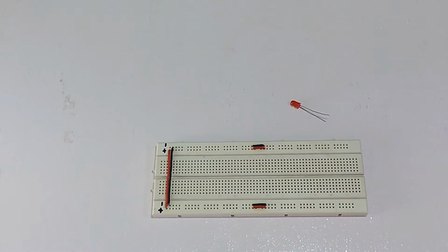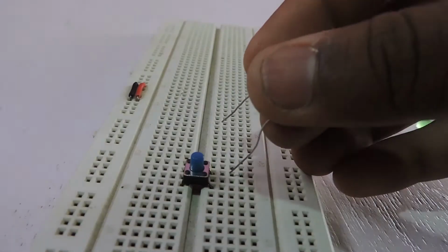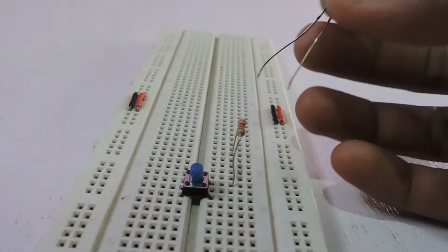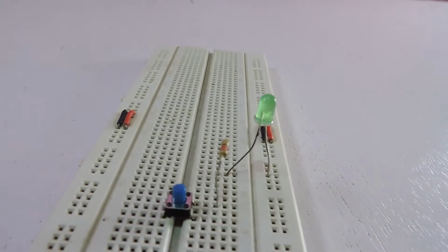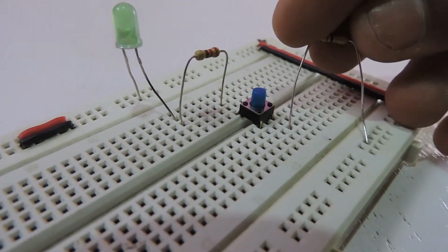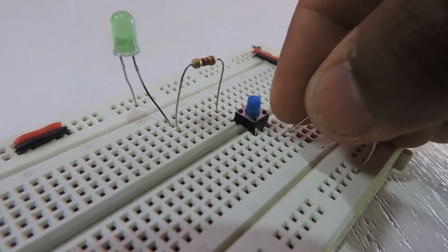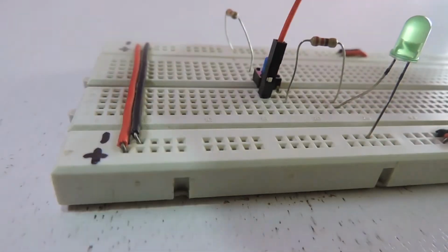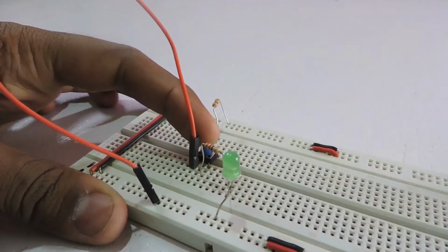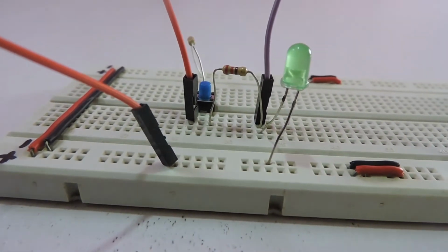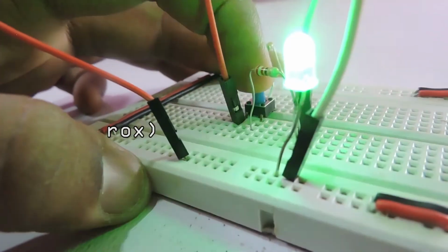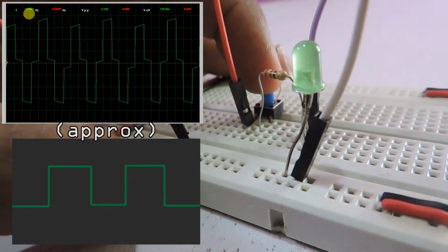We'll start from fairly basic. Just grab a breadboard, wires, switches, LEDs and a few resistors. We'll connect one lead of an LED to the switch and the other to ground with a 220 ohm resistor. Now connect a resistor of 10K from the switch lead to ground. Then connect the remaining lead of the switch to the power supply. Ta-da! You have a manual clock pulse generator. If you hook the positive lead of the LED to an oscilloscope, you can see a square waveform as you turn the switch on and off.